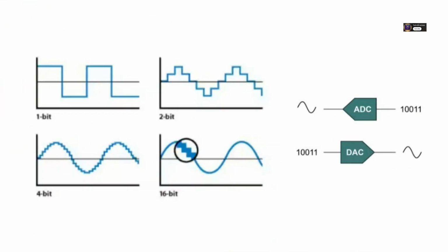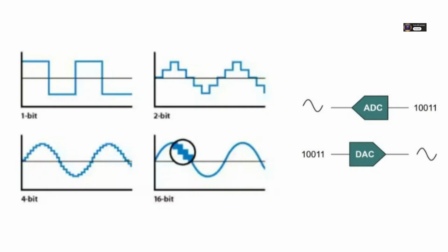You also mentioned something called step recovery time. Yes, step recovery. That refers to how quickly an ADC's output can accurately settle to a new value after a large, sudden change, a step change in the analog input. If your signal makes very sharp jumps, you need an ADC with good step recovery performance to make sure it doesn't lag behind or give inaccurate readings during those transitions. It's important for dynamic signals. Right, you don't want it to miss the jump.